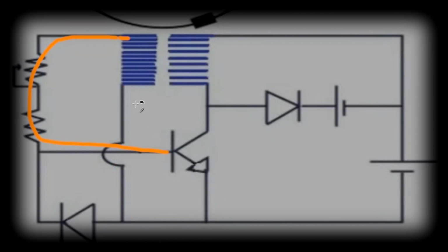And that would be this shot right here. Oh, okay. So you see the rotor magnet getting closer to the trigger winding. Once the rotor magnet falls over the drive coil, this is the point I need to make out here, that these two coils are wound in a bifilar around each other.